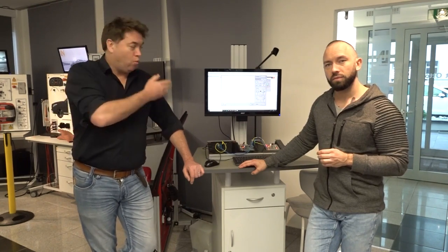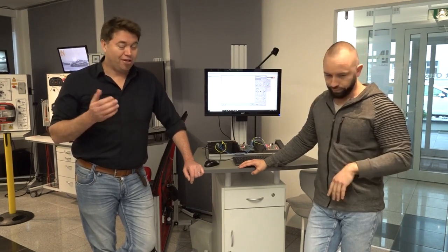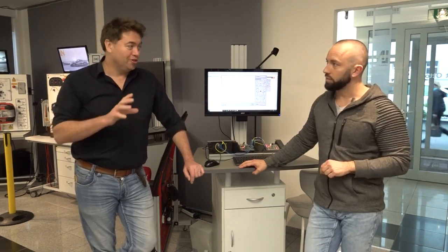But what's important is that if you just disconnect the control unit while it's awake, you can actually destroy the control unit. Someone told me they did that on a vehicle and they had to buy a new control node for $1,000. So it's not always the best method. But really understanding the oscilloscope is critical here.